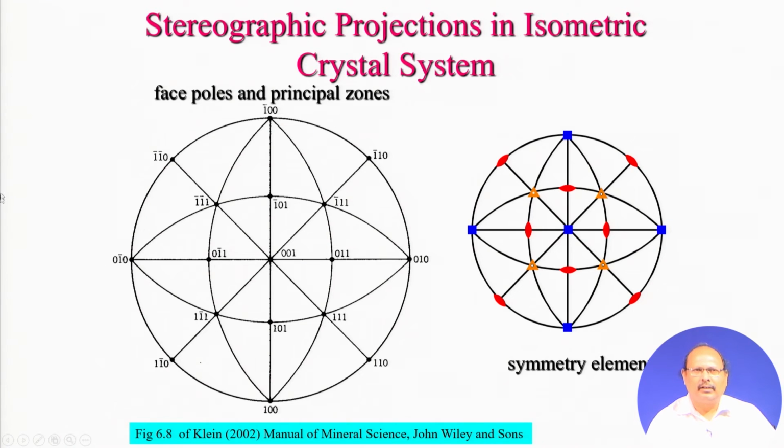So, students, please remember that you are now using certain bar symbol here. You remember this bar symbol refers to the negative direction of the corresponding axis here. So, when you have a bar symbol at the position of the C crystallographic axis, immediately we will be considering that it is intersecting in the negative direction of the C axis here.